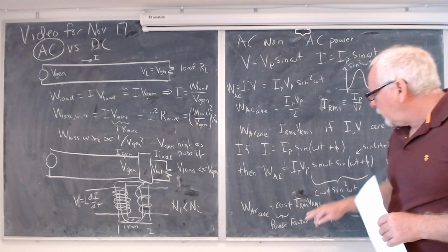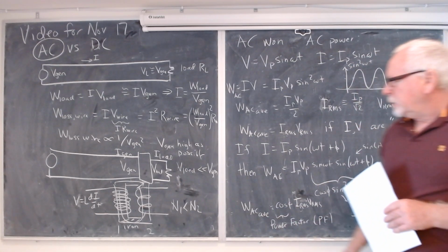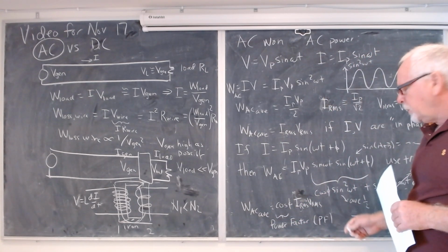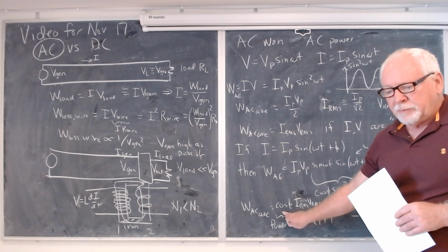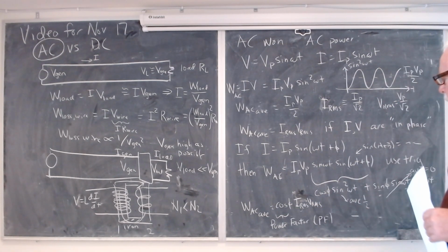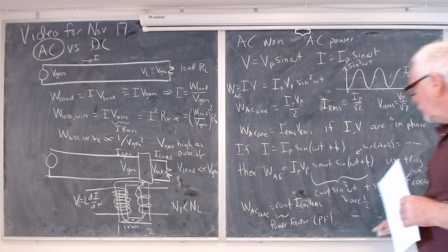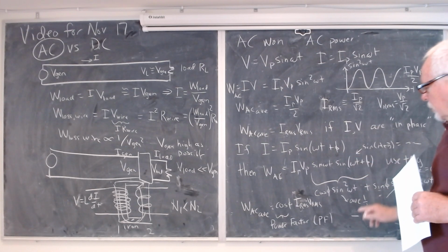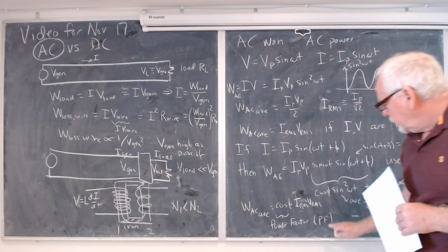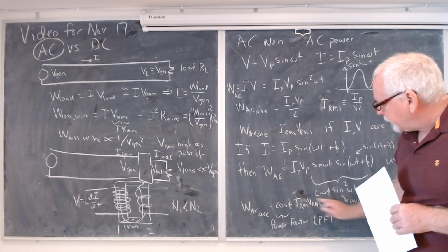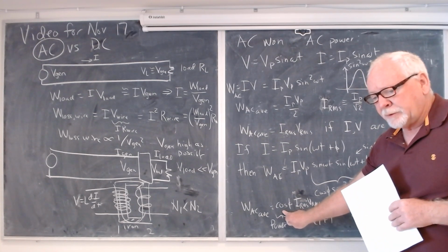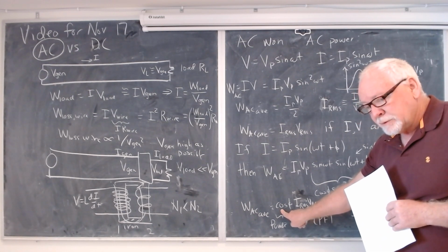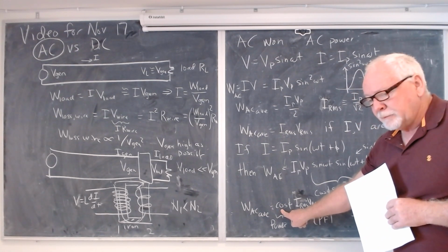And so when you calculate, well, we'll go through it more, but basically, like your little kilowatt hour meter, if you play with it, you'll see that it calculates power factor. And so if you have an out of phase circuit, like in your homework problem, the power then is still IRMS VRMS, but then you have to multiply times the power factor. And you see that if phi equals 0, the power factor is 1. So you revert back to your original formula.